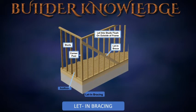Wall bracing. Bracing is used to stiffen framed construction and make it rigid in order to resist winds, storms, or twist and strain from any cause. It keeps corners square and plumb and prevents warping, sagging, and shifting from lateral forces that can distort the frame and cause badly fitting doors and cracking plaster.